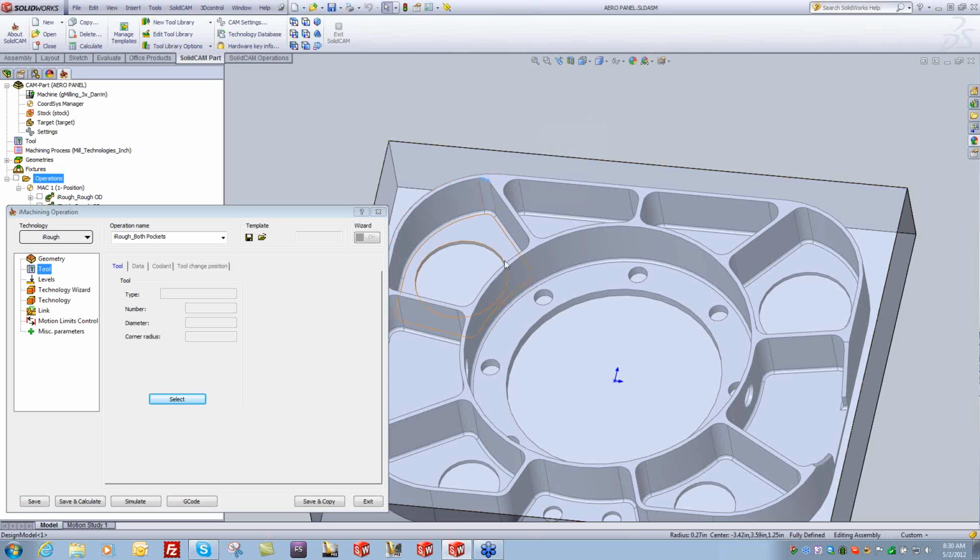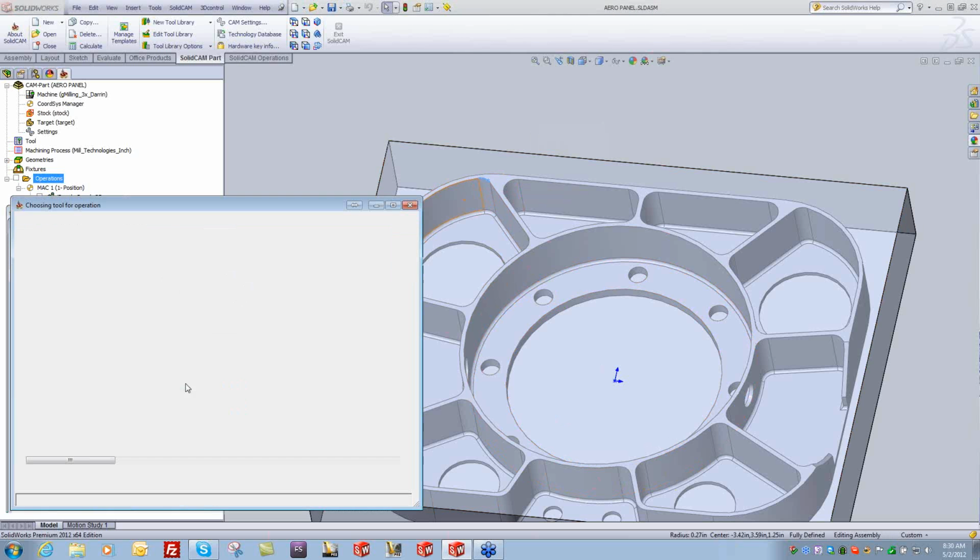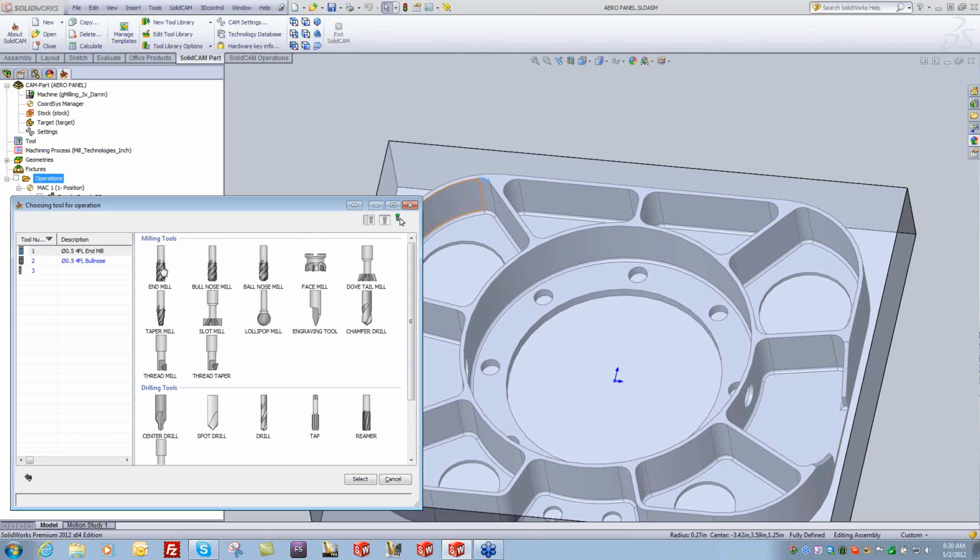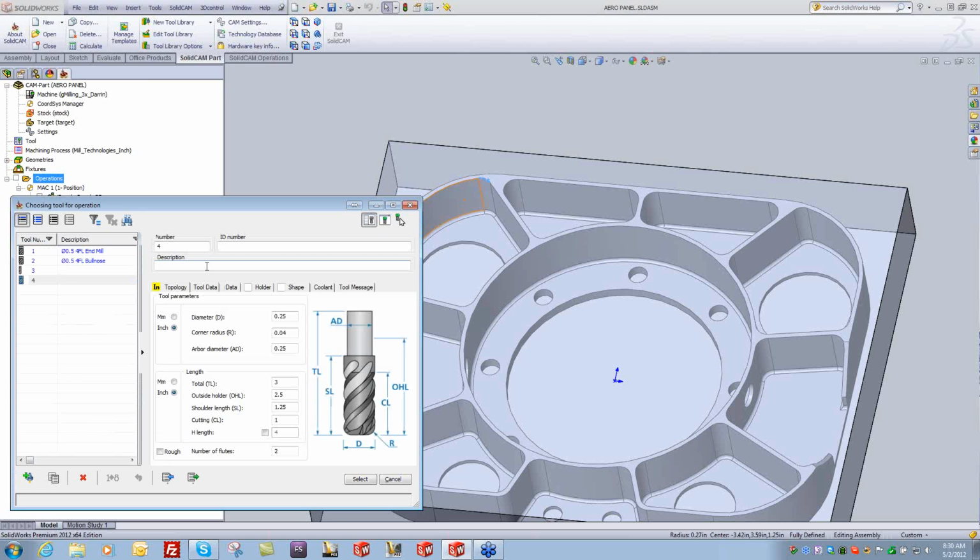This right here is a 270, so a ½ inch would easily cut that. So let's go ahead and put in, I don't know, a 750 cutter. We'll use a bullnose. By the way, that little symbol is holding down the Alt key and using the number pad, not the numbers above your QWERTY keyboard. Hold down the Alt key and type in 0216. There's different values you can do, like hold down the Alt key and hit 248. You get the degree symbol.